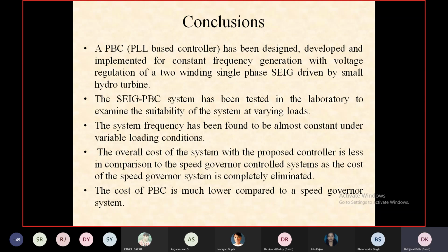You put a 1 inch or 2 inch diameter pipe, and you may convert a pump into a turbine, so the pump will act like a turbine. That is called the PAT system, pump as turbine system. So you just put some pipes, couple them with the pump-as-turbine system, connect it, and it will generate 1 kilowatt power continuously, day and night, without any cost. That is the beauty of the system.